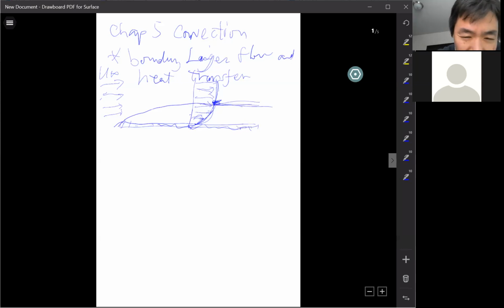Okay, so this region under this borderline, this curve I draw here, is called the boundary layer border. So you see the difference, right? Under this border, the velocity is smaller, and above this borderline, the velocity is the same as the free stream velocity. That makes sense, right? We separate them with smaller velocity and the normal velocity.